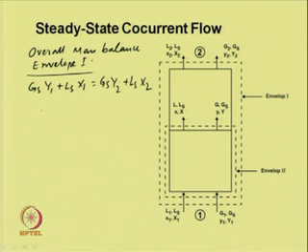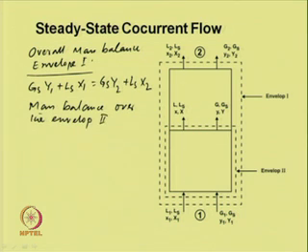and mass balance over the envelope 2, we can write Gs Y1 plus Ls x1 is equal to Gs y plus Ls x.